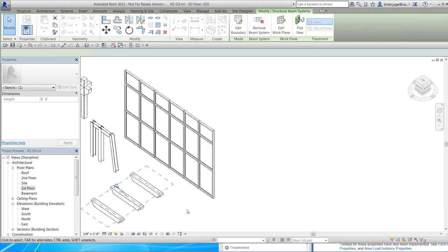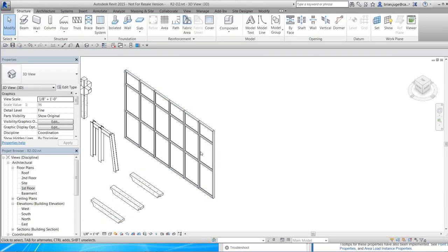I had just a couple of things. They've changed the way pins work and their identification within Revit. So any type of item that is part of a system that gets pinned, like mullions, panels, or beams in a beam system, you're going to see a slightly different icon letting you know that those items are part of a pinned element that's part of a system. So it's just an icon change. I wanted to show you because you're going to see it at one point in here. Does this work for any pinned element anywhere in Revit? No, it doesn't. It's only if it's part of a system.